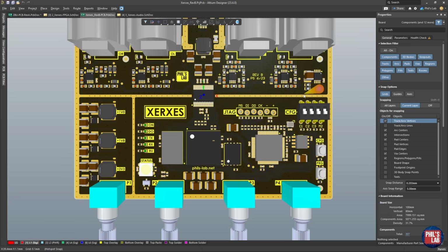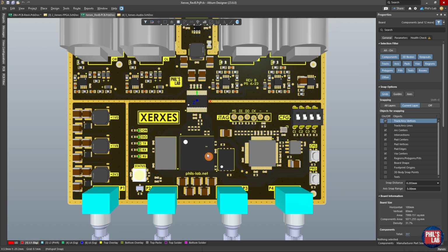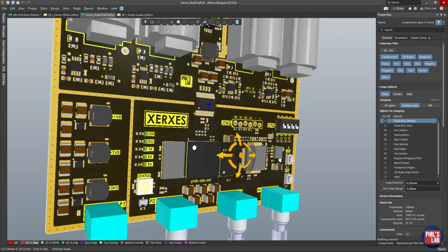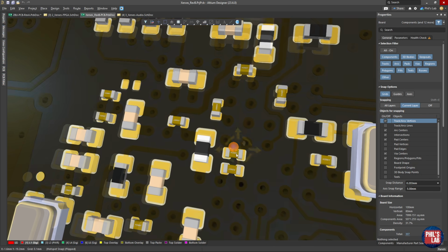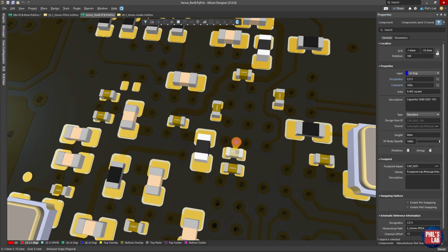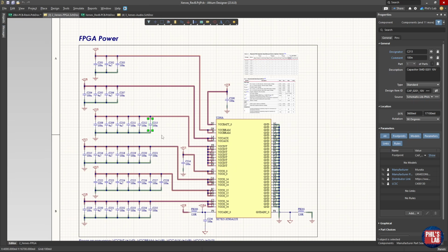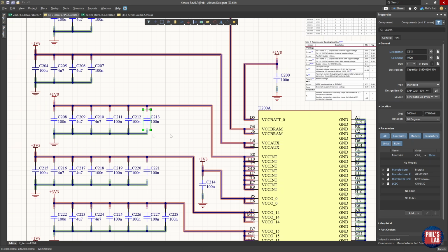Let's look at some very basic and brief examples. For example, for this FPGA-based hardware design, I have some decoupling capacitors on the bottom side of this BGA package. You can see these are 0201 parts because they had to fit between these through-hole vias on the bottom side. So that was already one limitation, which made me go to 0201 for some of these capacitances. Keep in mind that 0201 parts, because of their smaller package size, will have a lower inductance, of course, assuming they're mounted correctly. In the actual schematic, these are, for example, these 100 nanofarad caps here.